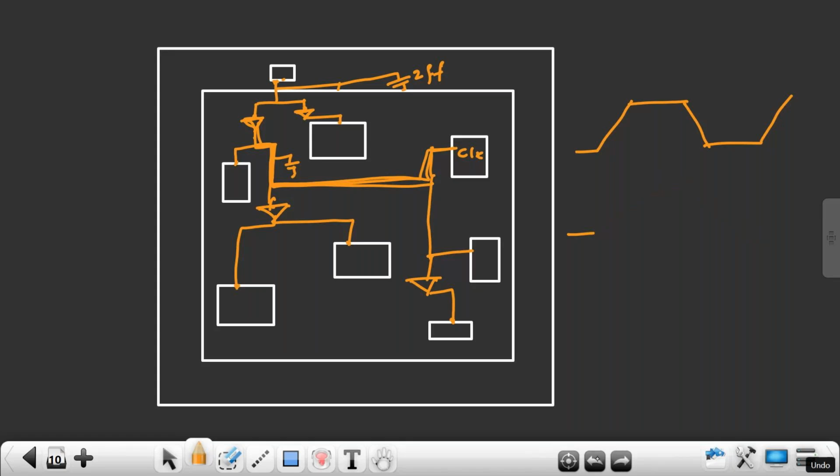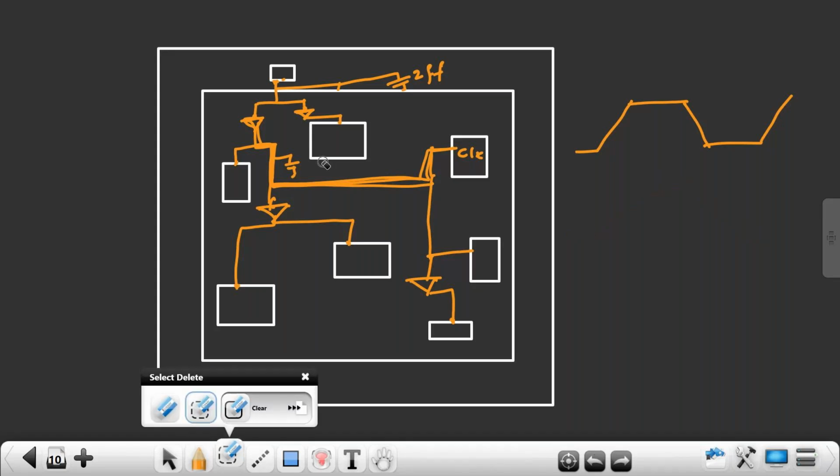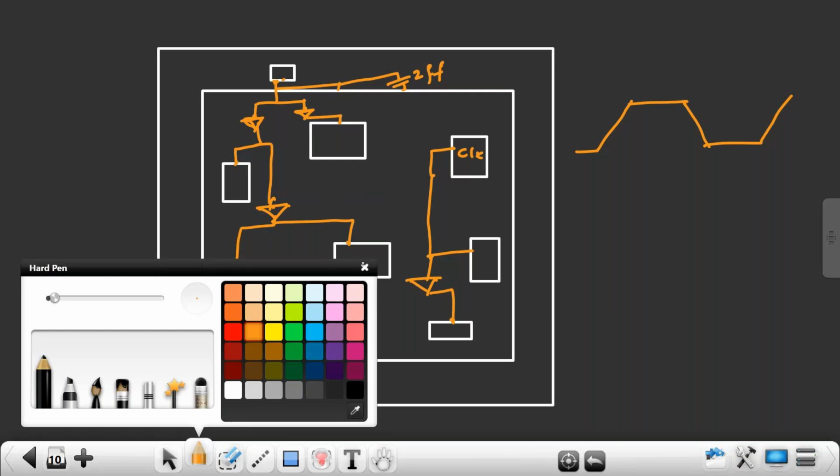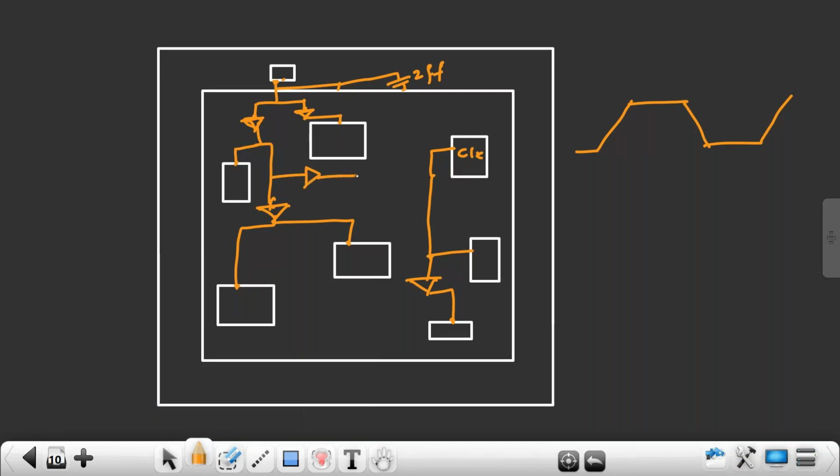So even net length is very important. Net length should not be very high. To reduce the net length, what do we do? Again start building the tree by inserting what? Buffer. So building the clock tree like this by inserting buffers in between is called as what? CTS. So clock tree is mainly built to reduce the load on what? Load on the clock port.